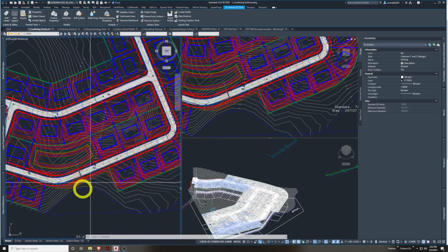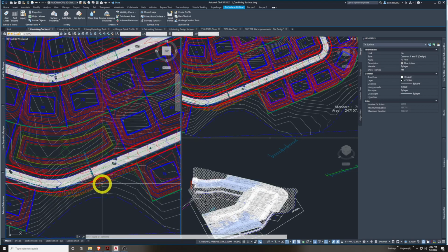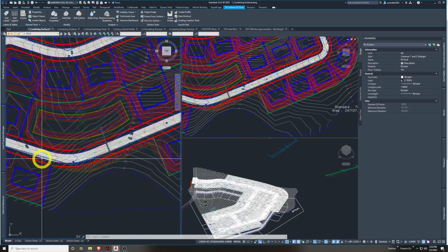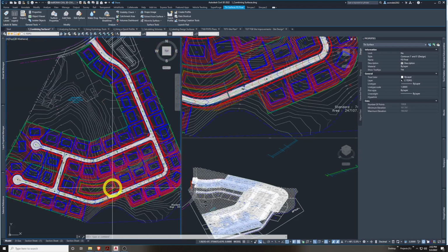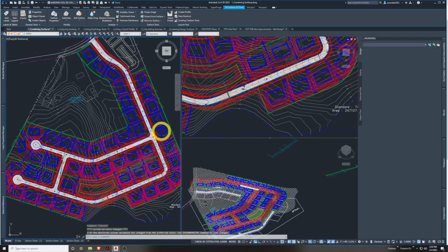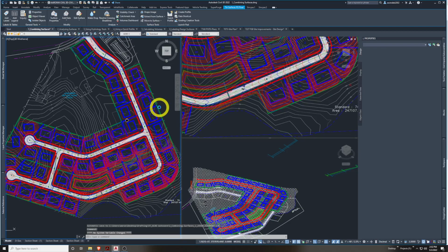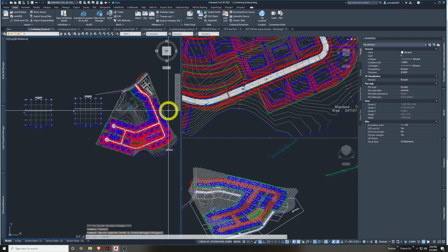So basically between lots 73 and 76, it added a little daylighting, grading, separate surface that just graded out to existing. So this is not a bad move to keep surfaces more simple, develop them in a modular fashion, away from each other, linked to each other in some ways. It's not always the worst. I'll show you some surfaces really quick that I did all in one because they were on one kind of tight site. There's a lot of ways to do this. This isn't a bad way how they did this to promote a more streamlined design, a less corrupt drawing.